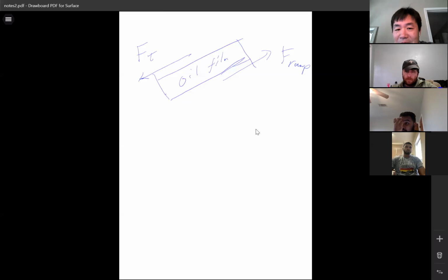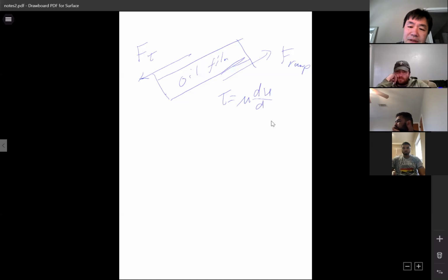So here, come back here. We're going to apply our equation. Which equation have we learned so far? This is the viscosity problem, right? Shear stress problem. What is the equation? Isn't it shear stress is equal to mu dy dv? Yeah, du, not dy dv. It's mu du dy, the velocity gradient.